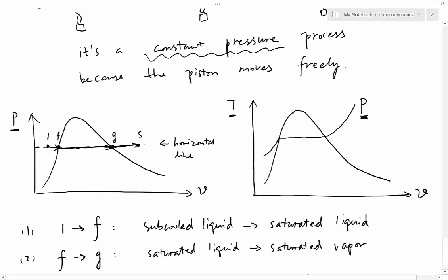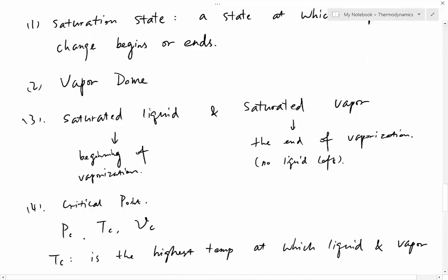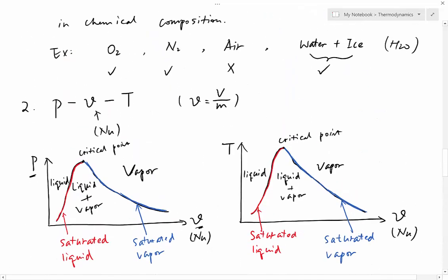Okay, let's start from point 1, which is my tap water. Where's tap water? Tap water, point 1, must be on this P line. And also, what's the phase? Liquid, meaning to the left of the vapor dome. Okay, if you forgot, let's go back to the diagram. Where's liquid on the T versus nu diagram? To the left of the vapor dome.